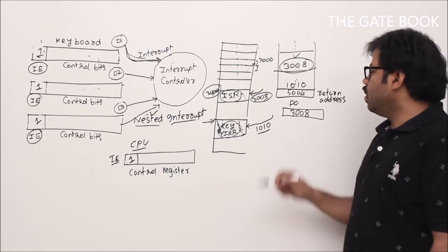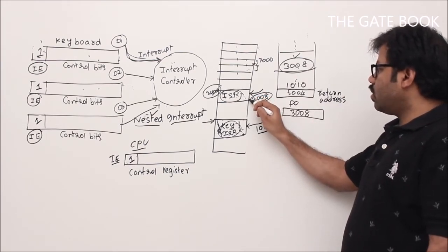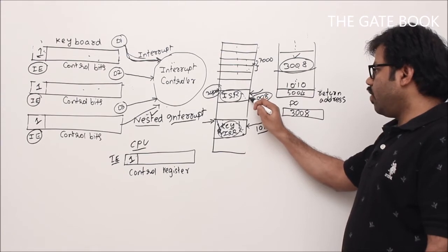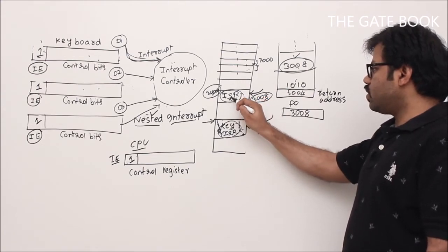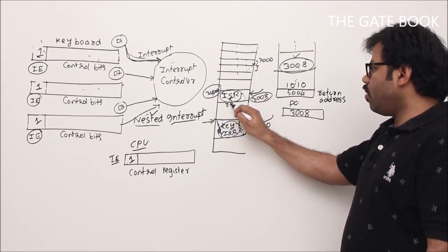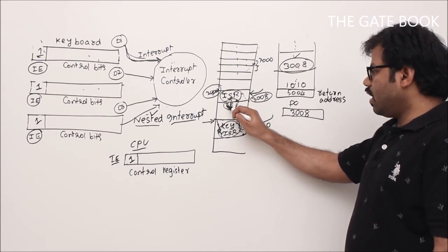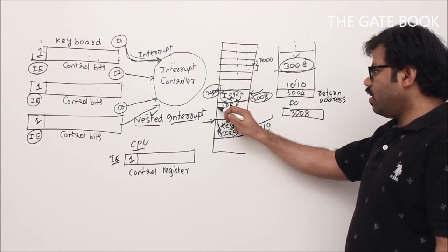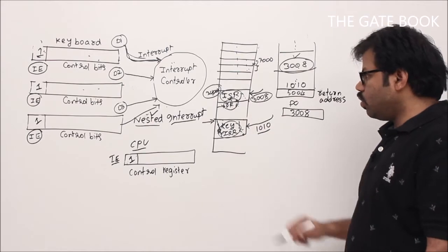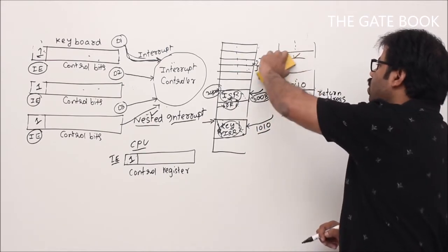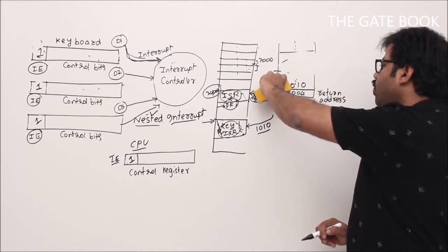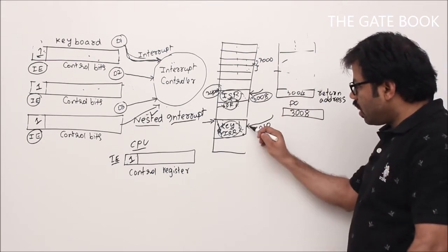Okay. Then blindly that processor will execute this program, right? While executing this one, once this interrupt service routine is done, there will be a return from interrupt, right? So whenever this return from interrupt is executed, it should pop one more return address, this time 1010. So because of that, control comes here.